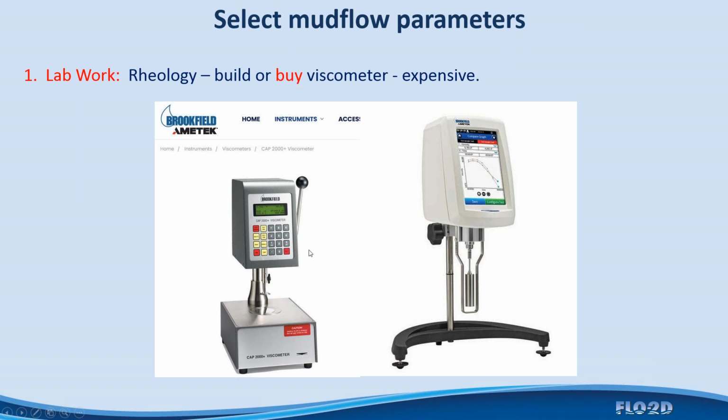And so what you want to do is actually create something that you're going to see. So if you had a velocity of 1 to 2 meters per second on the surface of the flow, then you could actually calculate that the vertical velocity gradient was something on the order of maybe 2 inverse seconds or 3 inverse seconds, depending on what you saw in your flood event occurring.